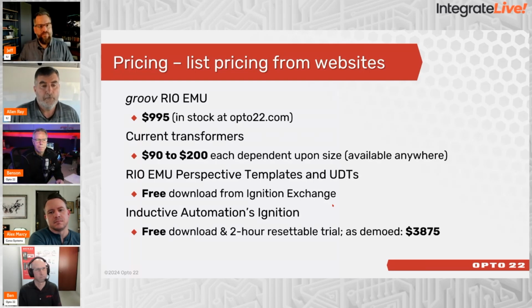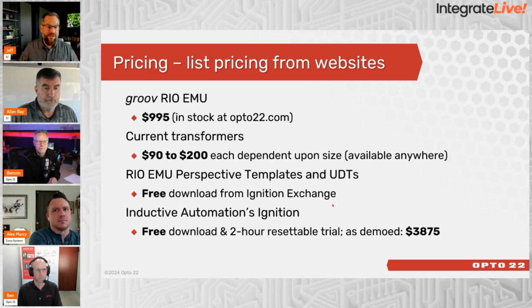The concept of, hey, you're publishing it to an MQTT broker, or you're an OPC UA server right now, I can create an event trigger that says when I start a new batch, grab the value. When my batch is complete, grab the energy value. I now know how much energy I've used per batch, which means I can start to understand my cost of goods a little bit better. I can start to understand how much energy it costs me to run these 1,000 units, right?